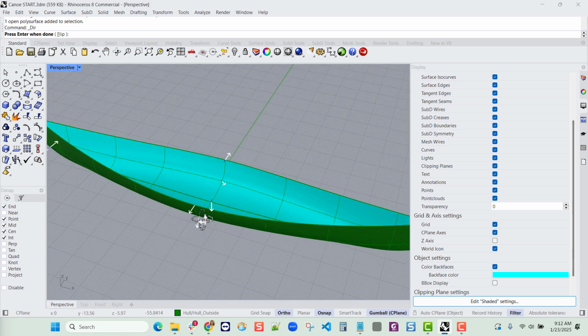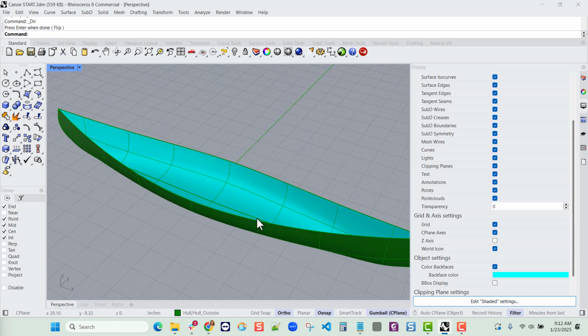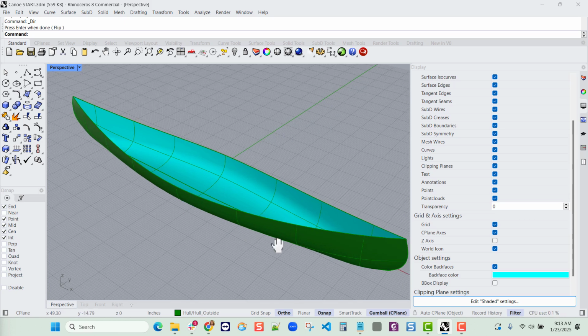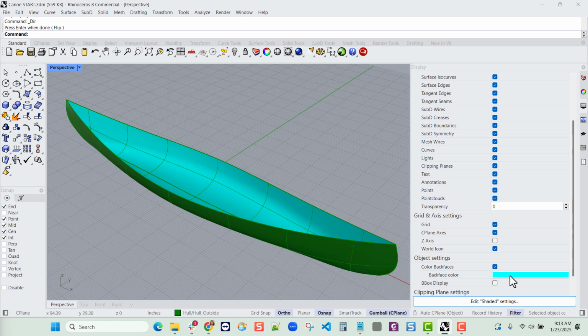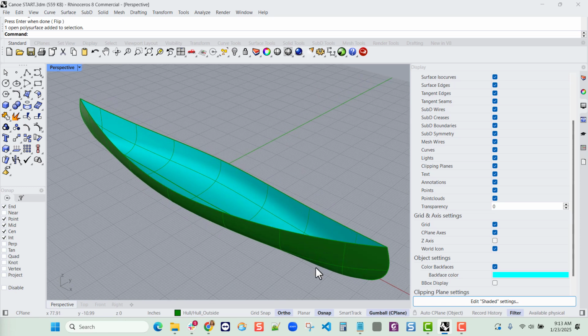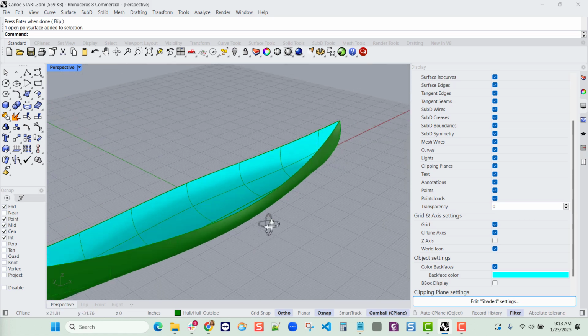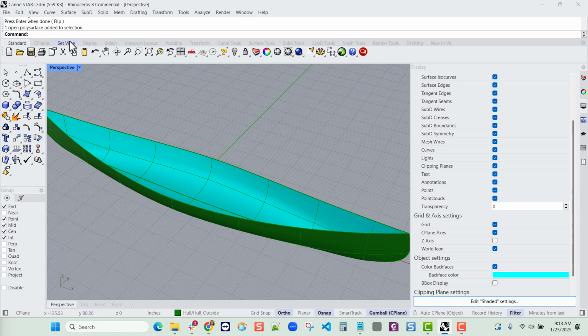So I can always go to the direction command, but if the front and the back faces are shading in the same color, I can't really tell what the normal is without it. So I like to do this. The two colors that I typically don't use for layers are yellow, because that's Rhino's highlight color, and cyan, because I find that it doesn't broadcast or record well. So I will use either of those for the back face color, and in this case, I've chosen cyan.